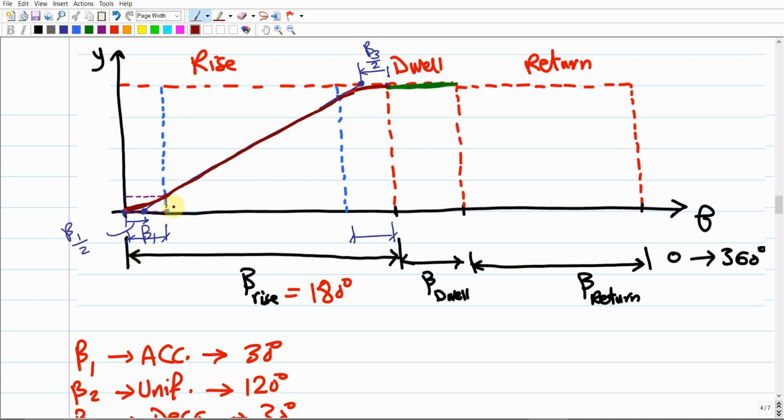But in case this width is bigger, you have to break it down and follow a similar approach as we explained before for the parabolic function, which definitely would take time. But for this course, and basically this is what conventionally happens, for this uniform motion we are focusing more on the uniform period. That's why the uniform period consumes the wider distance in comparison to the decelerating or accelerating period. So it is highly acceptable, as I said, to just connect these two with a curve. Making a curve by hand is highly acceptable. Then you can move to the return motion. Make sense?